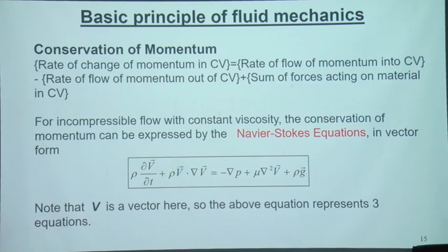The next one is the conservation of momentum. Again, for incompressible flow with constant viscosity, we have the Navier-Stokes equations. Everyone knows about that. This is the acceleration, this is the convection term, and then the force terms, usually including the pressure gradient and the viscous force, and also the gravitational force or any other external force relevant to the problem that we solve.